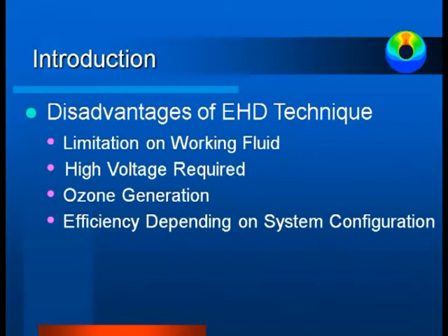But EHD doesn't have only advantages. It has some disadvantages. One of the disadvantages is that we cannot apply it to all kinds of working fluids. We can only apply it to dielectrics, so the fluids cannot conduct electricity.